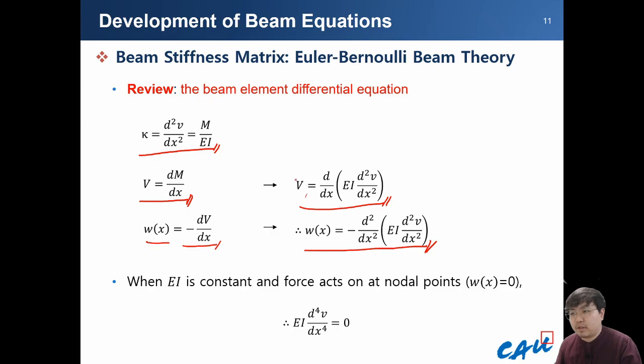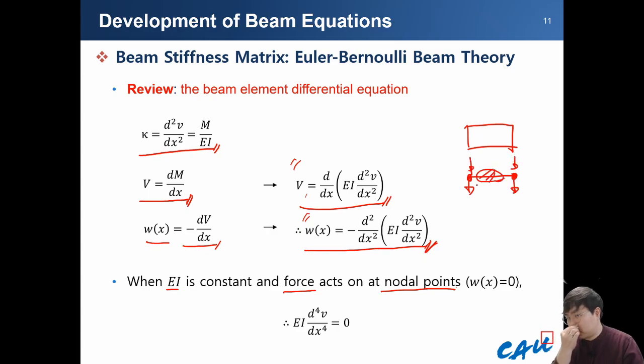So finally we reached this relationship. When we assume that Young's modulus and the moment of inertia are constant and the force acts only on the nodal points, it is because in the FEM simulation we only consider the nodal displacement and nodal forces. Inside the element we don't have any information, so the distributed force is always equal to 0. So finally we obtain this relationship here.